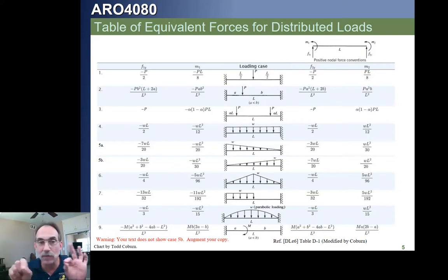So regardless of how the beam is constrained, if we have a beam element used anywhere in our model, we're going to use that simulation we just developed for a distributed load. In the same way, if we have a beam element with any of these other applied loadings, now we're just looking at the loading, we're not looking at the end constraints. We're going to imagine that this is a continuous beam element, therefore we're going to use the fixed case, simple case like what we see in the appendix of our 3261, 3271 handbook to develop our loading function.